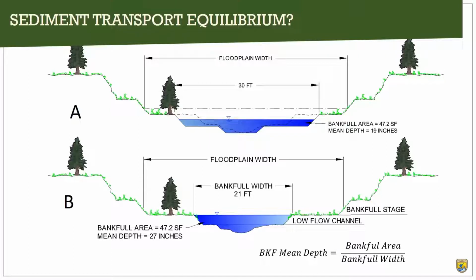By maintaining the hydraulic geometry, it flows up to the bankfull stage. Basically we can maintain sediment transport in equilibrium between the crossing and the natural channel. So I think as engineers, we often want to design a bigger channel, convey more water, but that decision actually has an impact on sediment transport and can cause problems.